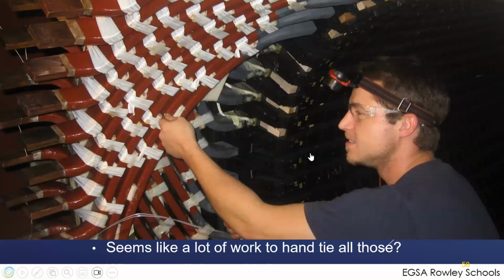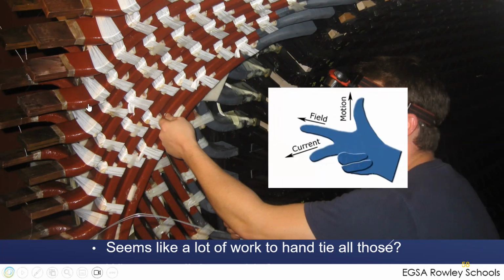And here we are stitching these together again. These are all tied and stitched in order to prevent these forces from ripping them apart. The other one was kind of laced together with almost like a needle and thread combination. This is hand tied with this special fiberglass tape, pulled real tight, knotted, twisted, tied, and then glued in place to hold all these windings together, because this is a tremendous amount of force if you have a fault.